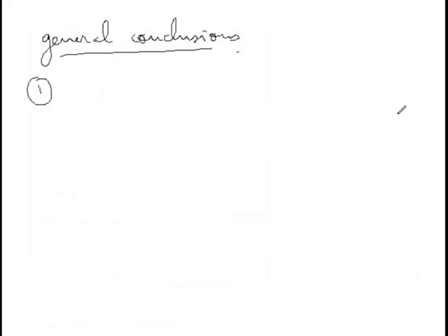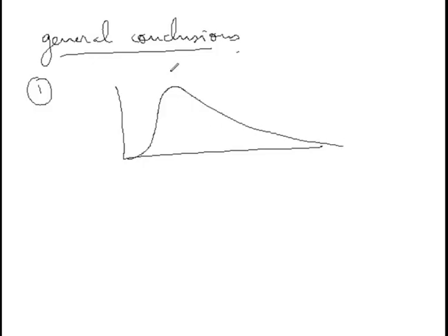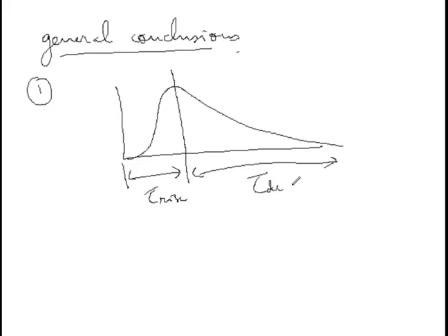This is interesting. What I am saying is that if I have a signal pulse like this, this part is the rise time, tau rise, and this part is the decay time or fall time. This rise part is independent of the circuit features. However, the decay time depends on the time constant of the load circuit, tau.